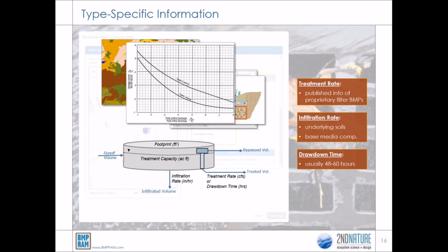Or flow rates through the orifice can be measured using various techniques such as bucket tests, current meter, flow sensor, or others. All of these field measurements are an investment of time, resources, and equipment to perform. The field measurements introduce some bit of sampling error also, and therefore relying on available literature can be acceptable for most BMPs when design documents are not available.